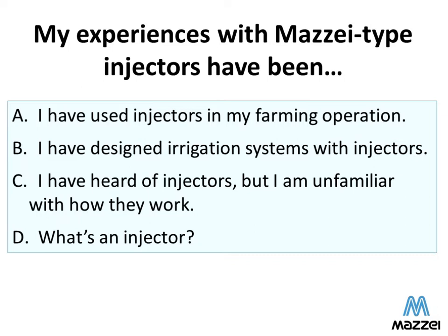Okay. Well, yes. To give you the briefest answer, the change in the downstream pressure will affect the suction capacity. A way that you can overcome that is to put some kind of regulating device on.